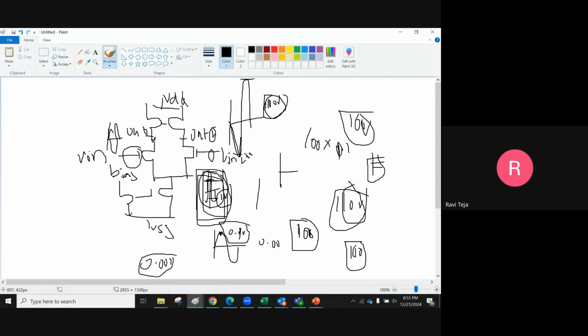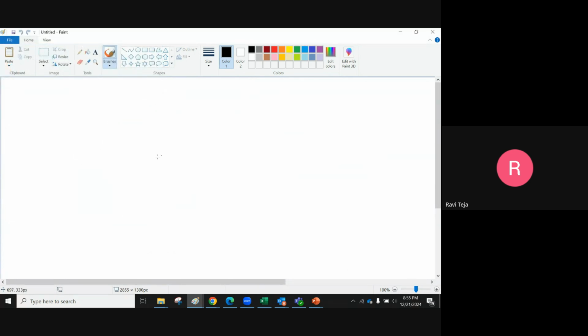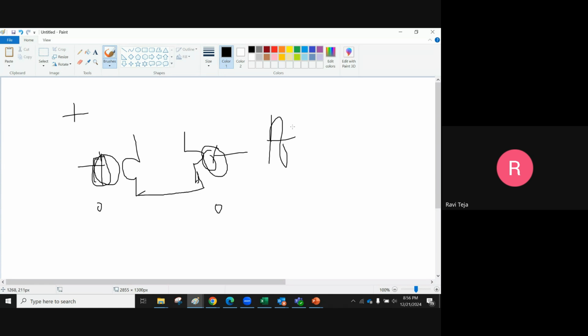That is too technical, but generally speaking, I will not draw the entire op amp, I will draw only the differential pair. I don't want any noise on these nets, or if I have added any noise in this, I need to add the same amount of noise here. Then both noises will be cancelled and the output will be the desired one, what we want. Either of the things we need to do. For that you need to match parasitics, you need to match everything.